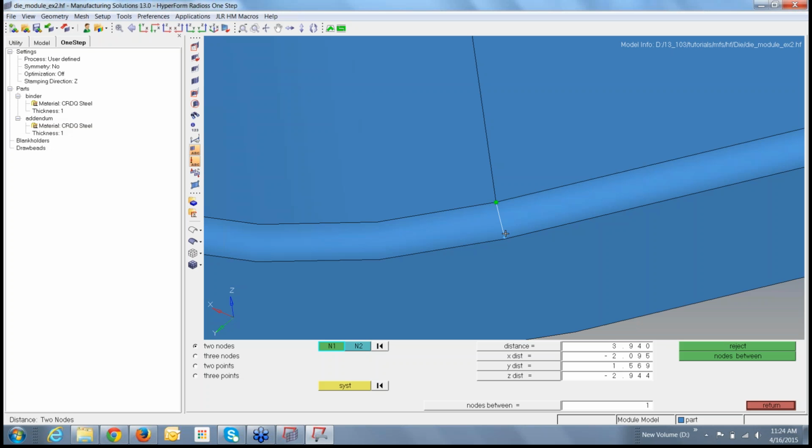So you need to always ensure that you are following consistency in your unit system. Everything has to be with respect to the same unit system. For example, if your model is in millimeters, then the density value has to be in terms of kg per millimeter cube. Your stress values will later be with respect to Newton per square millimeter. So you need to always follow a consistent unit system.